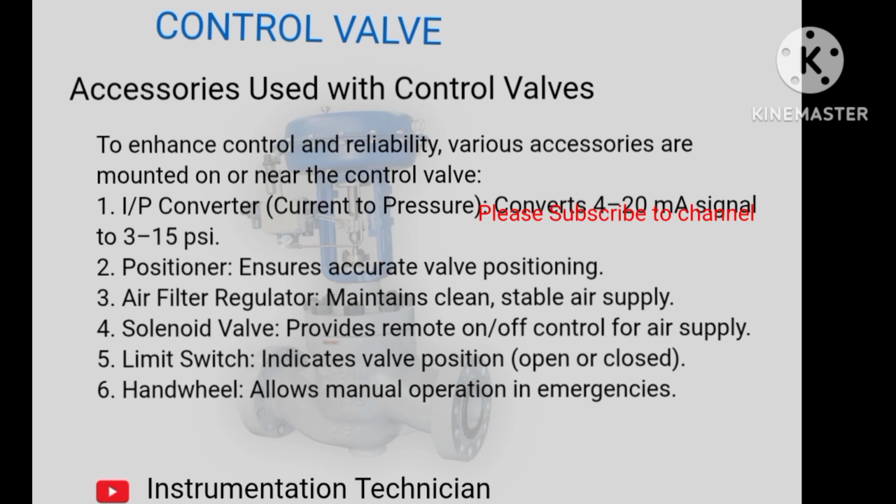Solenoid valve, provides remote on-off control for air supply. Limit switch, indicates valve position, open or closed. Handwheel, allows manual operation in emergencies.